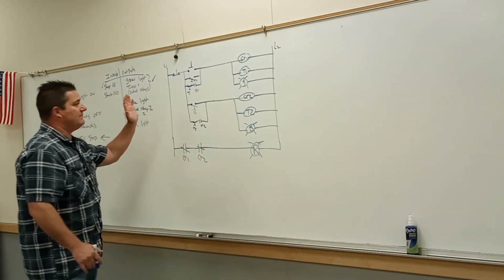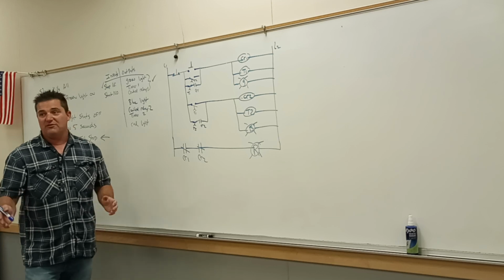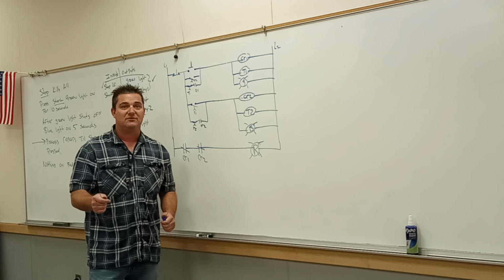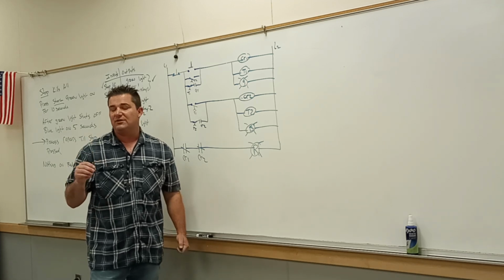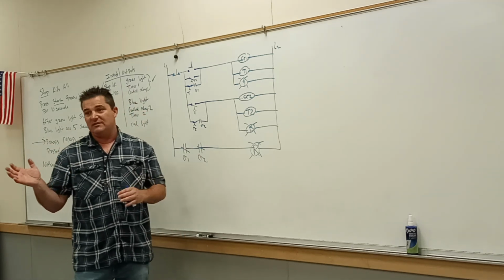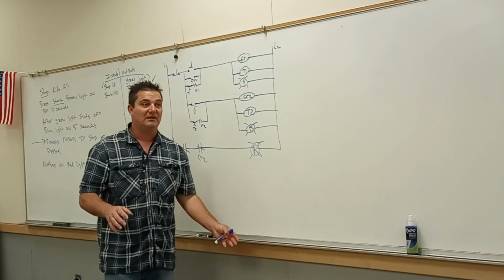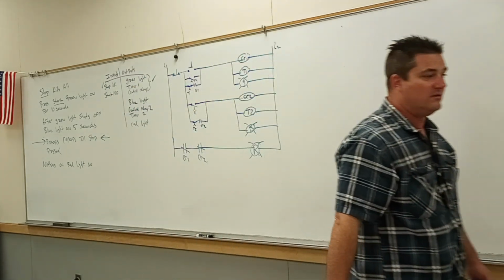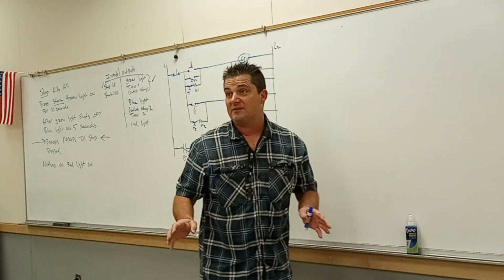So, Mario, would these be on delay timers? On delay for this one. Yeah. You've got to remember, on delay timers start timing as soon as they get the signal. Off delay timers start timing as soon as the external control switch gets opened up. And some relays and timers have instantaneous contacts, and some of them are time delayed. So that's why it's good to look at your Ugly's book on pages 126 and 27. There are lots and lots of symbols.